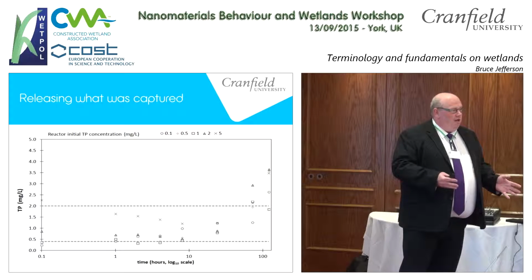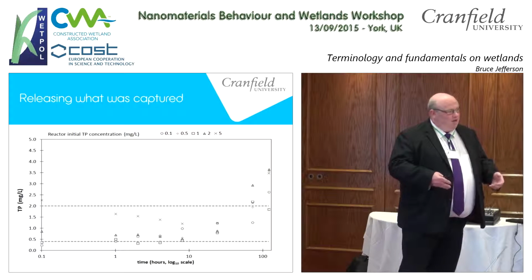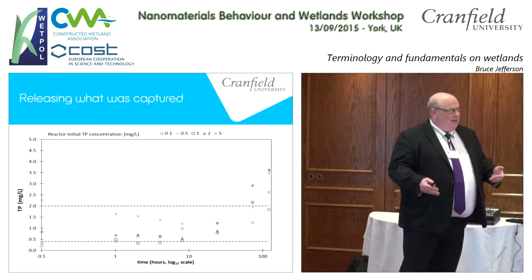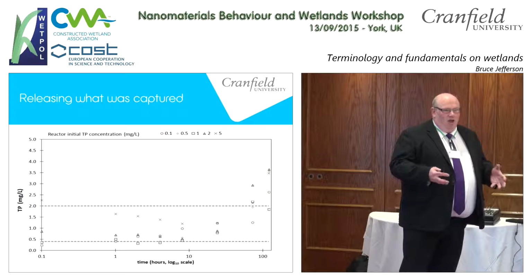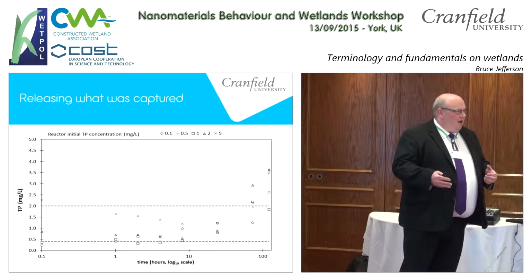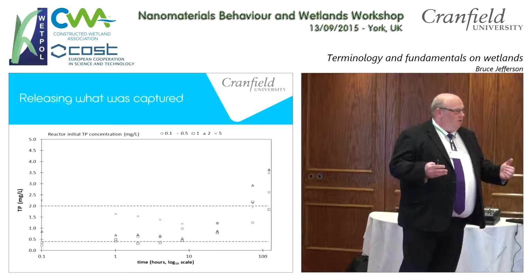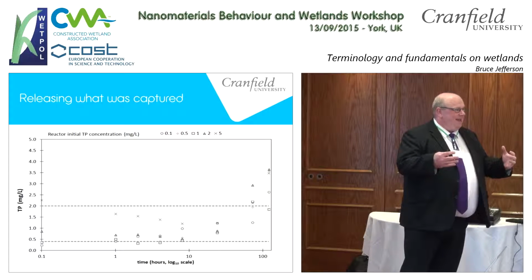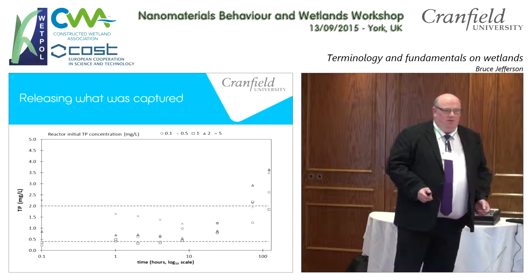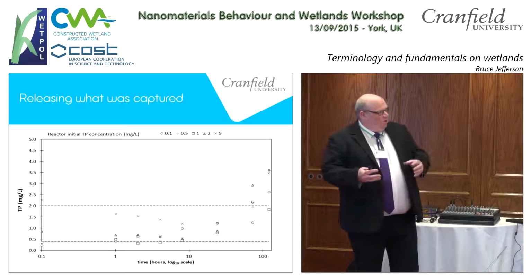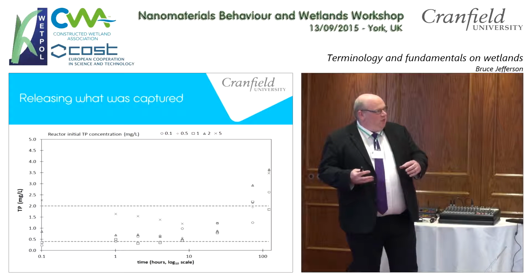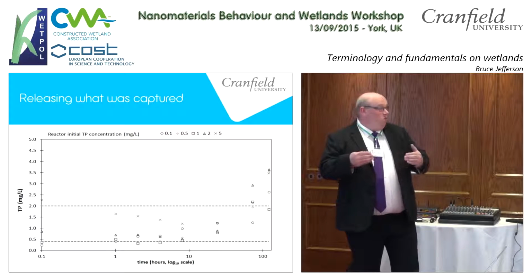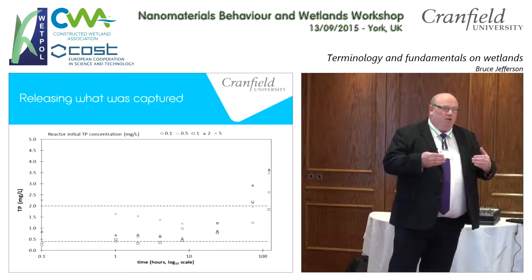And what happens over time is, as they get solid loaded, they ultimately switch from aerobic to anaerobic, or through anoxic to anaerobic. Under anaerobic conditions, I'm able to use iron reducing bacteria and I suddenly release a load of iron and phosphate. So what was a stored amount of material then becomes available back into the liquid. So not only have I got to think about how are the changes and what happens in terms of fate in removing, I do have a potential re-release source here, which would be quite uncommon in a lot of other types of systems.